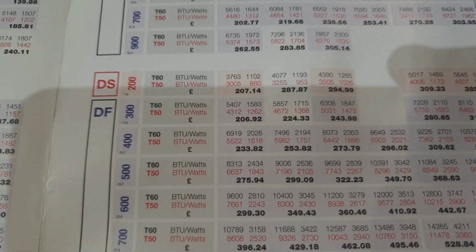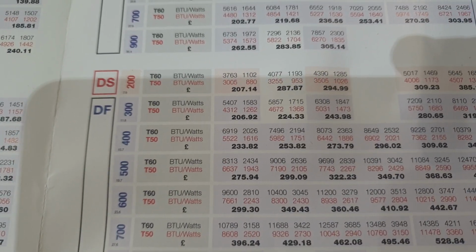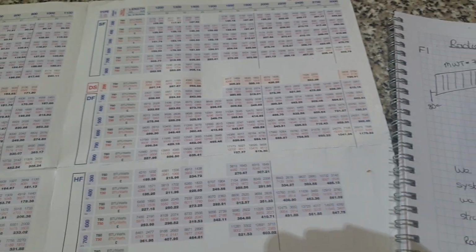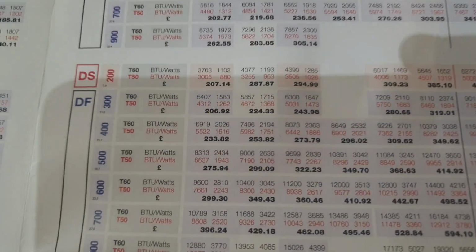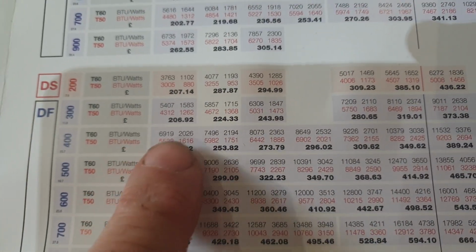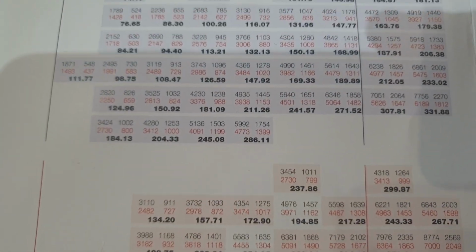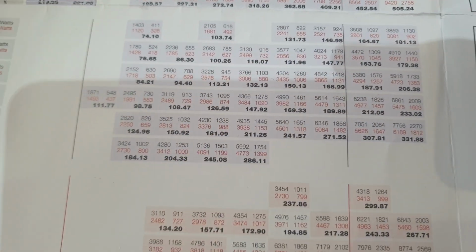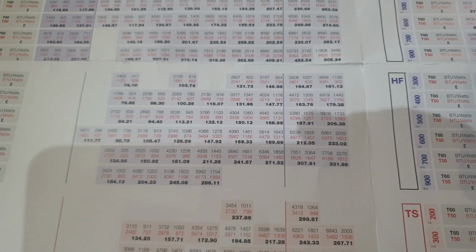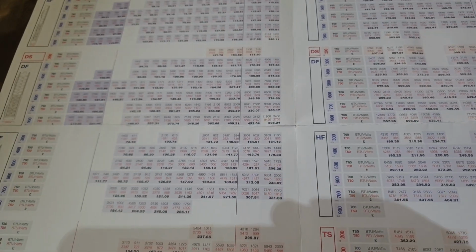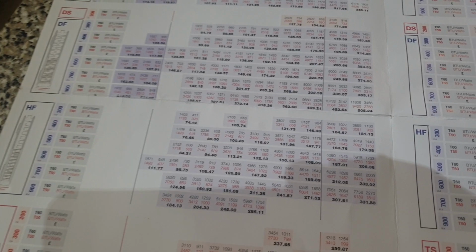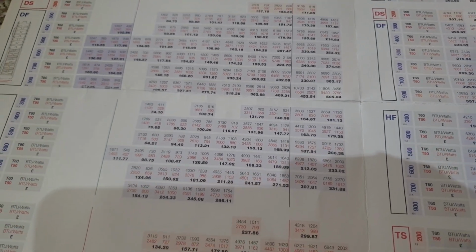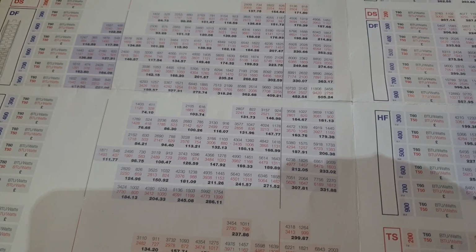Now that's a column a lot of people don't know exists, don't know what it means, and ignore. And they'll do their heat loss calculation. They'll get a room. I'm going to use a 1000 watt radiator for this example today. And they'll go to the catalogue and they'll search down the catalogue for a radiator with an output of 1000 watts. Somewhere in here there'll be one. Not that it matters. Anyway, they'll look for a radiator with an output of 1000 watts. They'll screw that to the wall, and that's a radiator sizing done. But unfortunately it's not the case, and that radiator is probably incorrectly sized, and that would depend on a few other factors such as F1, F2, F3 and F4.